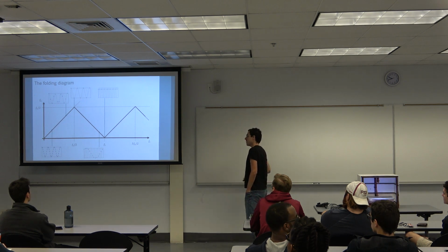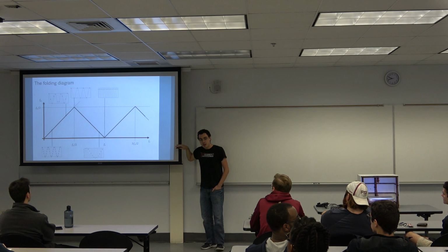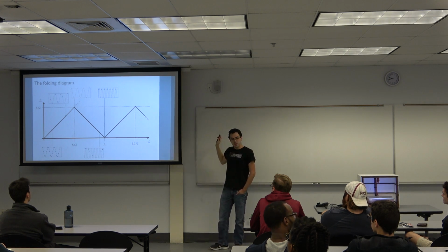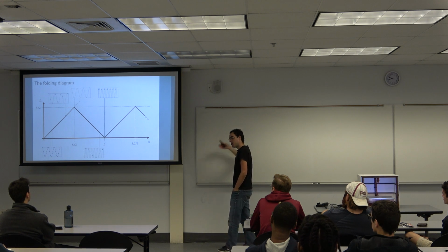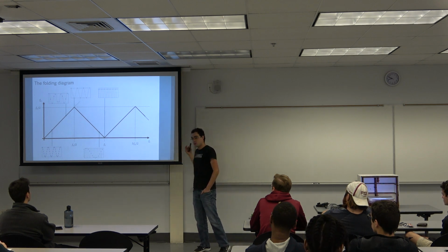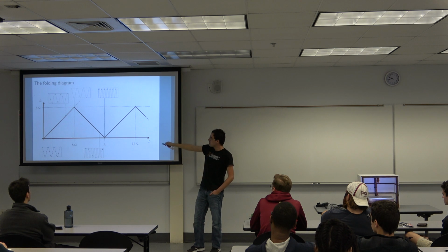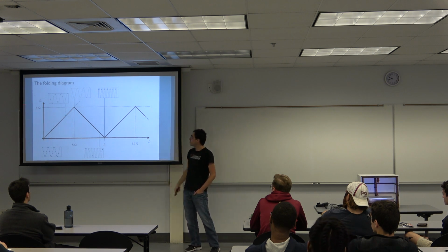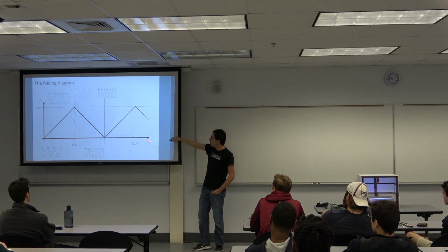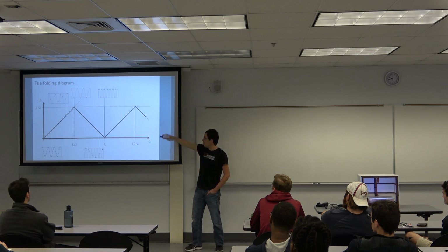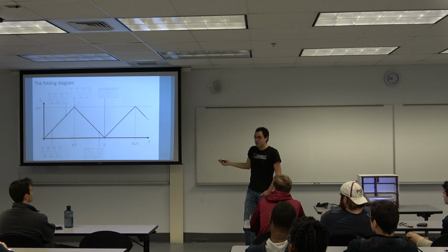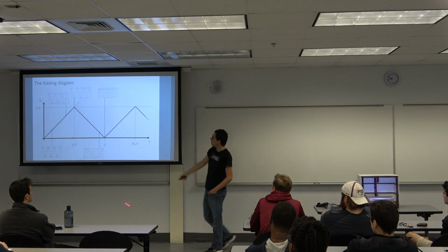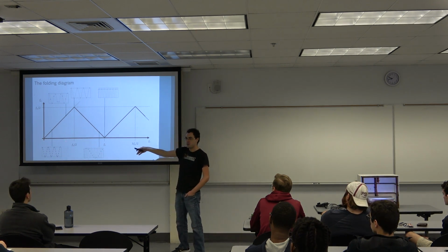And this is important because any phenomenon can have whatever frequencies. We can have frequencies on our electrical signals of megahertz, gigahertz, and those frequencies are there. Since we're sampling at a finite sampling frequency, those frequencies are going to appear within our sampling bounds, but they're going to be wrong. So we need to remove this frequency content, and this is the takeaway of this chart.